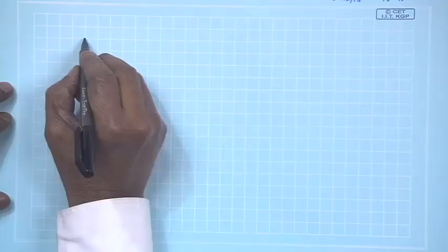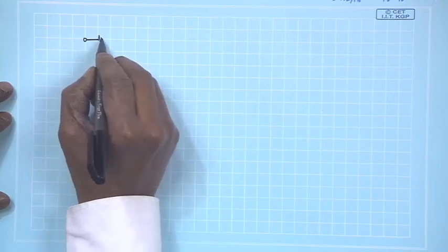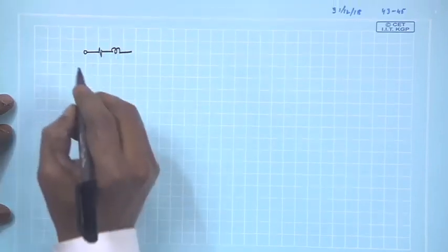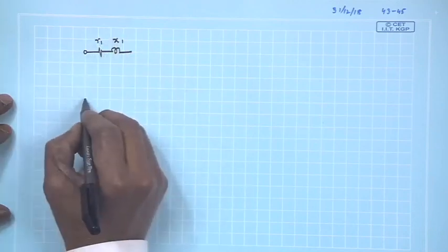on a per phase basis, and from that looking at the power flow that takes place in the machine, starting from the supply source to the mechanical power developed by the motor. So, we developed this equivalent circuit, which has stator resistance and stator leakage reactance per phase.